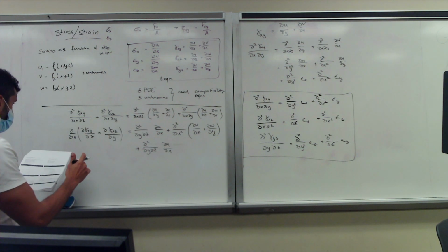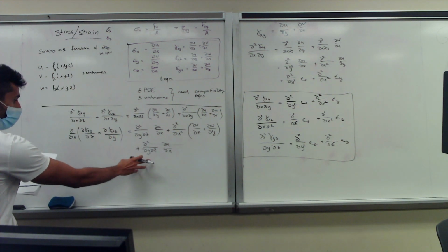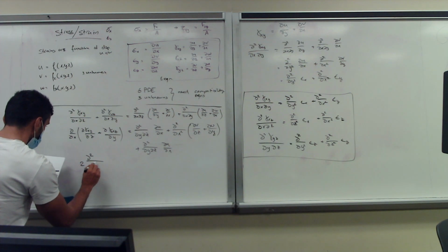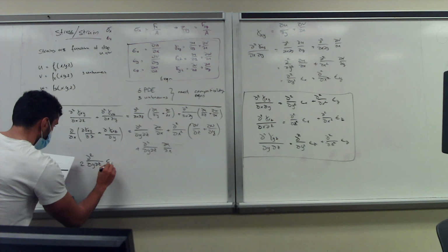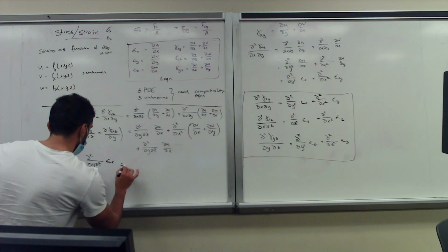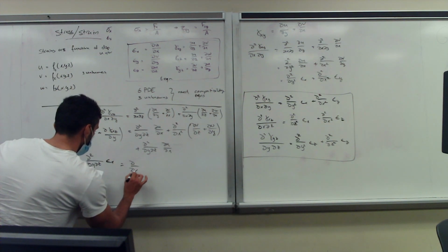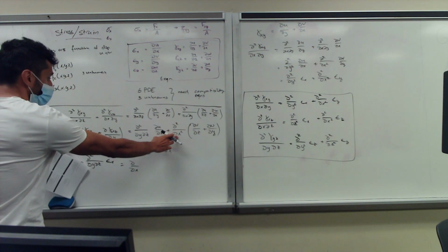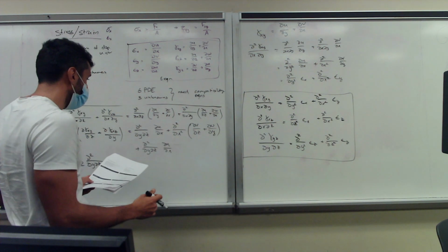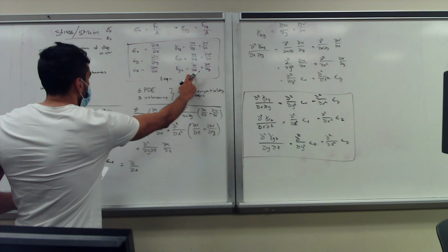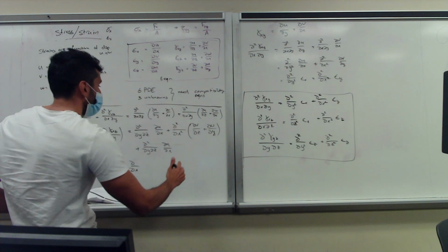We can take epsilon x to the other side. We have a 2 here because this is the same. So we get 2 times the partial y partial z of epsilon x is equal to, so we know that all of these have partial x involved with it, so we can take that out of the bracket, and we can rewrite this as gamma yz.